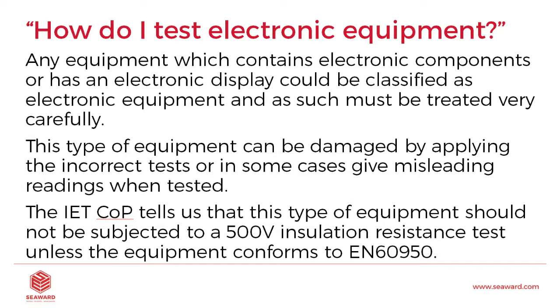So the IET Code of Practice tells us that this type of equipment should not be subjected to a 500 volt insulation resistance test.